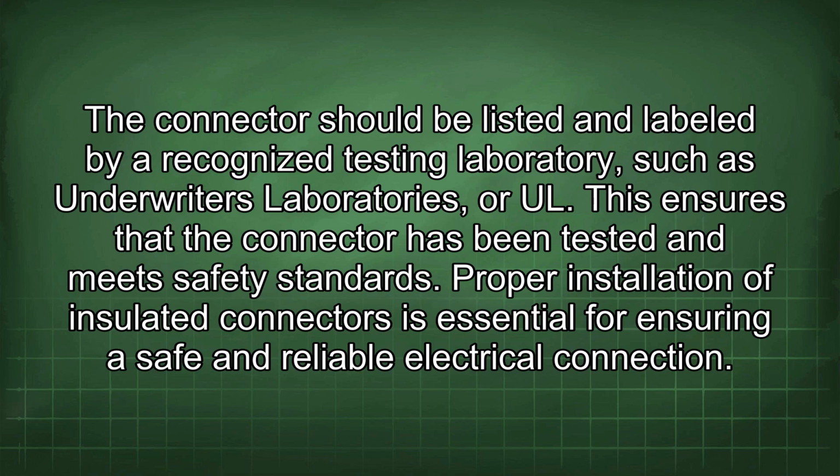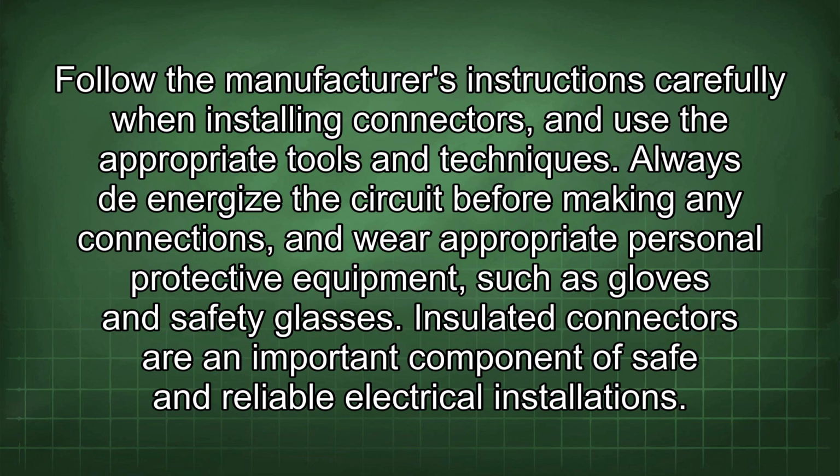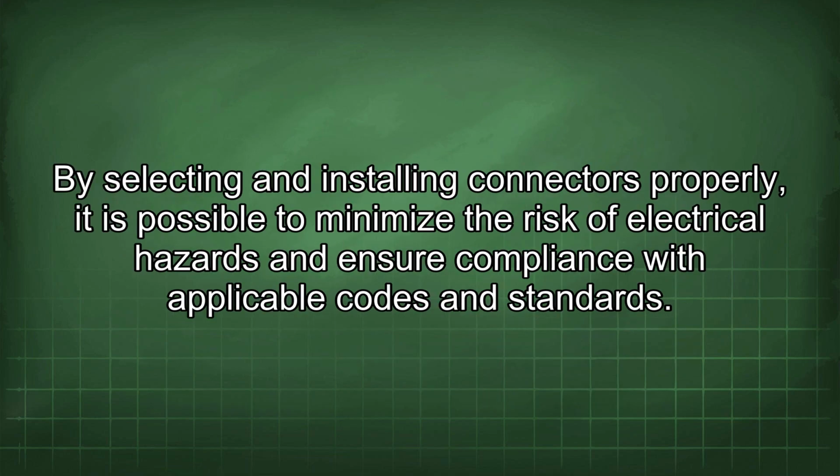Proper installation of insulated connectors is essential for ensuring a safe and reliable electrical connection. Follow the manufacturer's instructions carefully when installing connectors and use the appropriate tools and techniques. Always de-energize the circuit before making any connections, and wear appropriate personal protective equipment such as gloves and safety glasses. Insulated connectors are an important component of safe and reliable electrical installations. By selecting and installing connectors properly, it is possible to minimize the risk of electrical hazards and ensure compliance with applicable codes and standards.